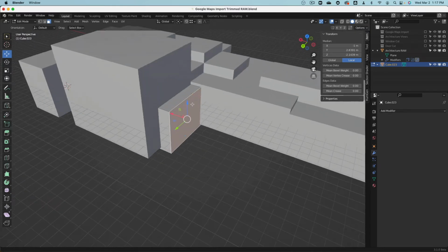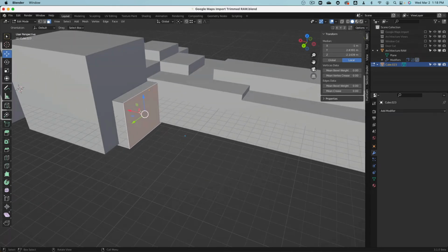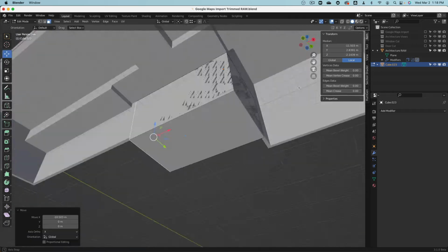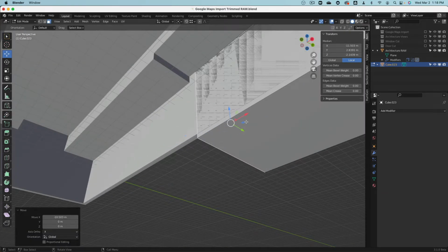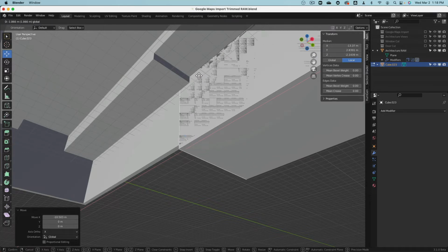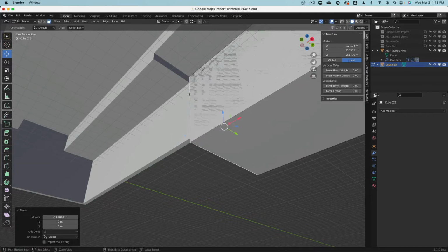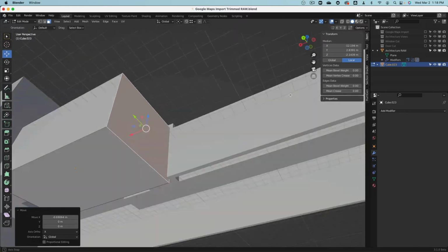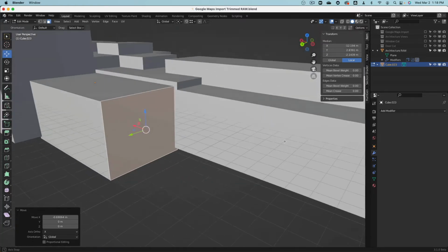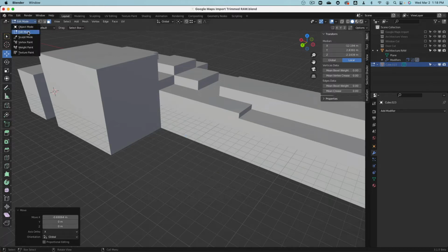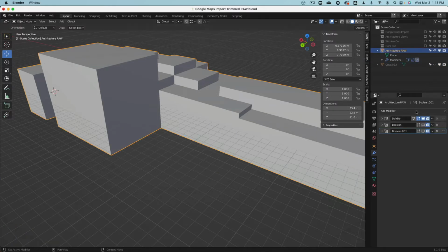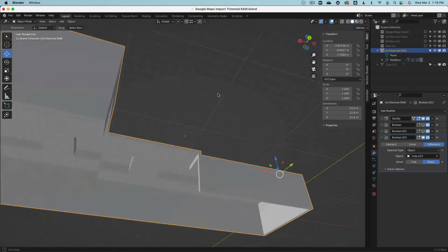And then this I can move along until this face is flush with there. So move along the x-axis, hold control, move your mouse to there, release the control button. Okay, good. So I want to hide this. Leave edit mode. Select this, go here and say Boolean, one more object, this cube.